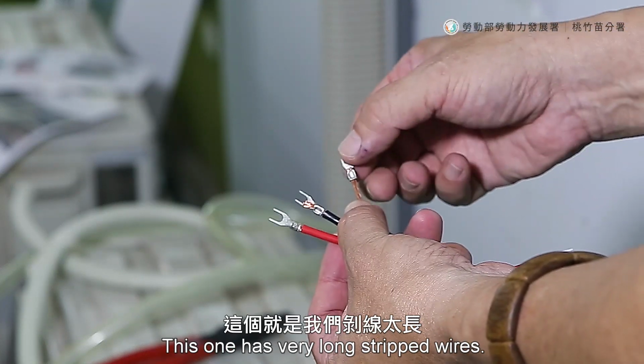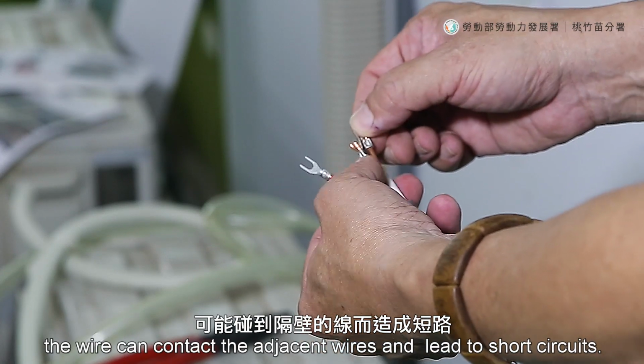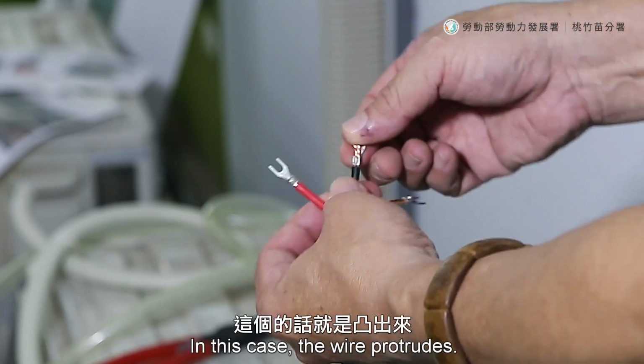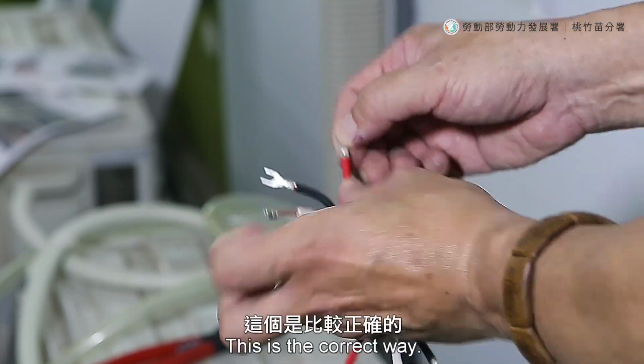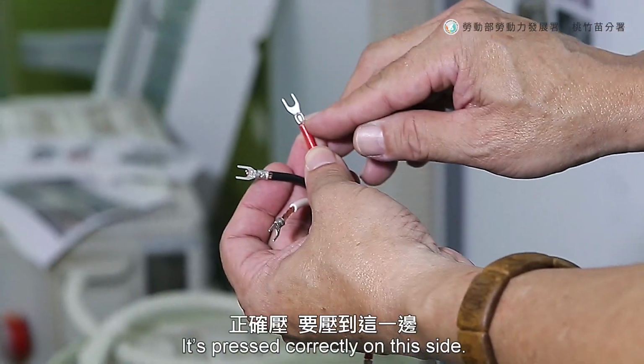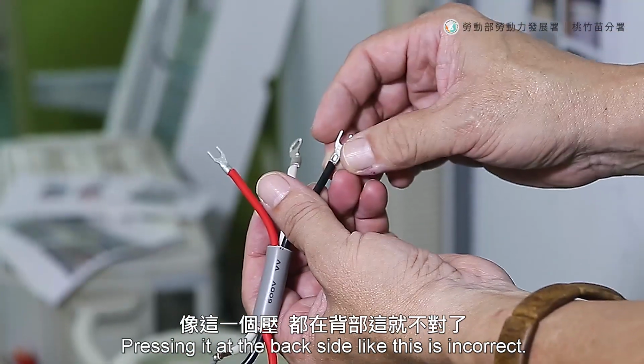This one has very long stripped wire. It's too long. When the AC operates, the wire can contact the adjacent wires and lead to short circuit. In this case, this wire protrudes. It sticks out. This is the correct way. It's pressed correctly on this side. Pressing it at the back side like this is incorrect.